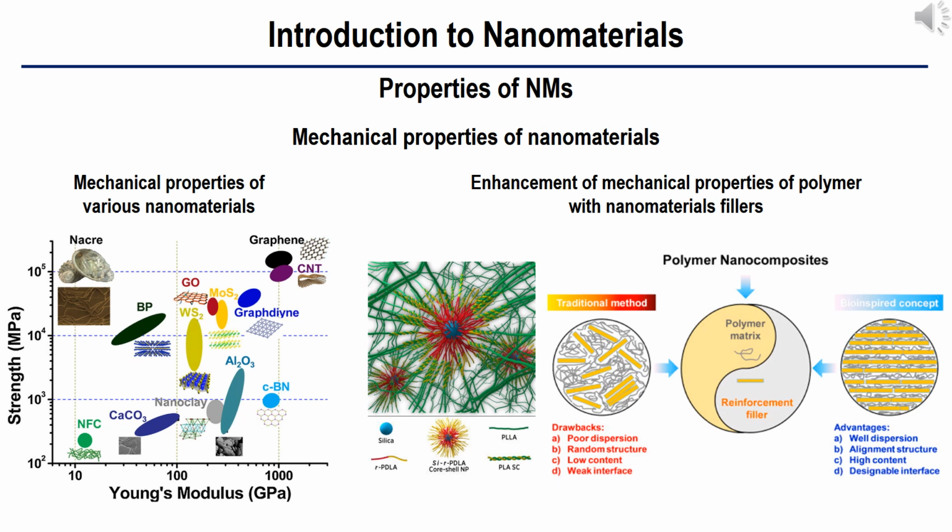The discussion of mechanical properties of nanomaterials is, to some extent, only of quite basic interest, the reason being that it is problematic to produce macroscopic bodies with a high density and a grain size of less than 100 nanometers. Experimental studies on the mechanical properties of bulk nanomaterials are generally impaired by major experimental problems in producing specimens with exactly defined grain sizes and porosities.